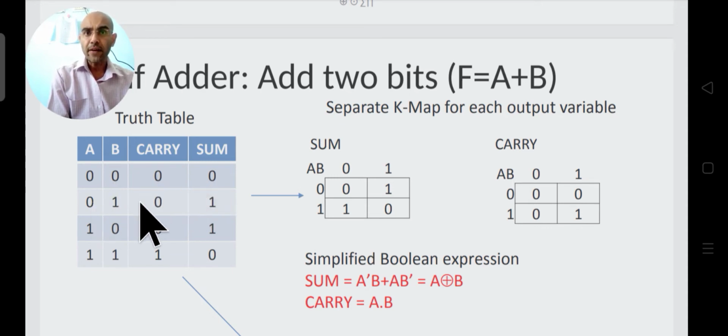Okay, if I add the other case, 2 variables whose values are 0 and 1, then the sum will be 1. There will be a sum, but no carry forward will be generated. So that is written like this. Again 1 0, same as 0 1, no carry, sum will be 1. But if I make both the variables 1 1, then the output will be sum 0 and carry 1. So 1 is carried forward, so carry is generated in this case, and the sum bit is 0.